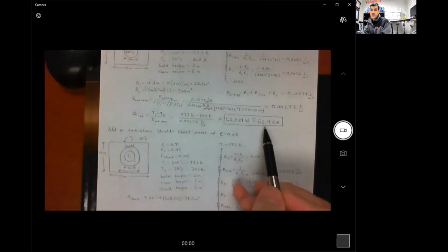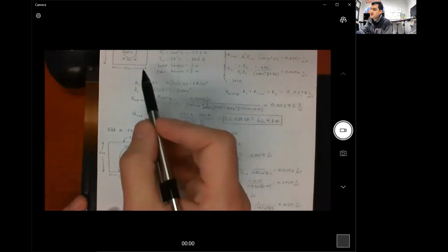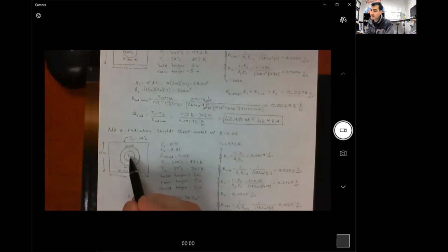So if I'm losing that much thermal energy, then I've got to burn a lot more fuel or come up with a lot more heat somehow, whether it's burning biomass material. Yeah, it says it's a biomass boiler. So you'd have to burn a heck of a lot more biomass material in this case than you would in this case to maintain the same temperature inside the boiler and get the same amount of steam. All right, so that would always apply. It's always better to have a more efficient system. That way you have to provide less thermal energy input, regardless of whether that energy input is coming from the sun or from biomass or nuclear or coal or natural gas or whatever. So your input costs and impacts are lower.